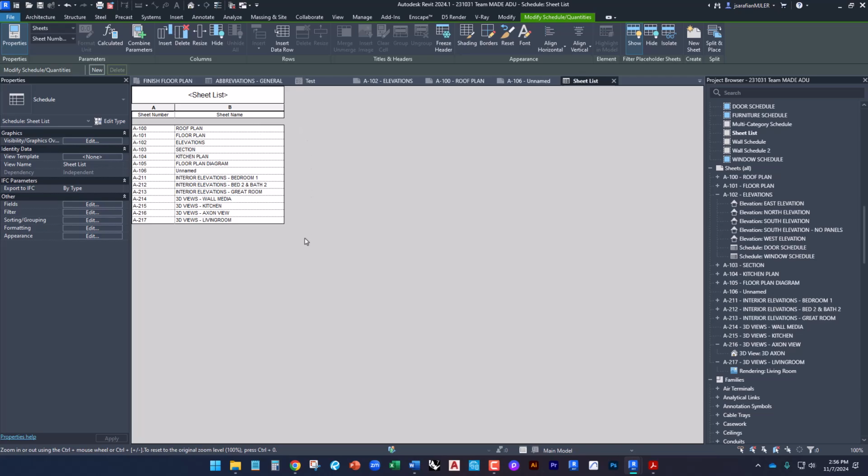And I'll add all of those numbers to this column, and I'll tell this schedule to sort these two columns based on this third one that I create. And then I'm going to go hide this third column. So this workaround is kind of a cumbersome one, but it's something that Revit still hasn't fixed all these years later. So let's talk about that.